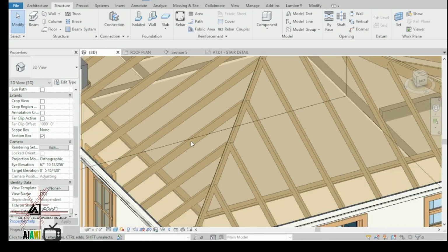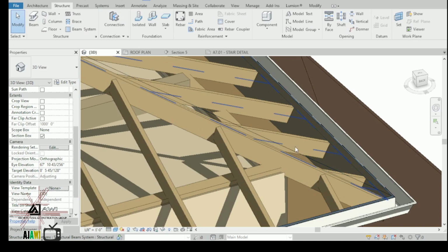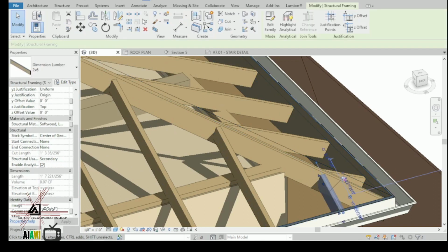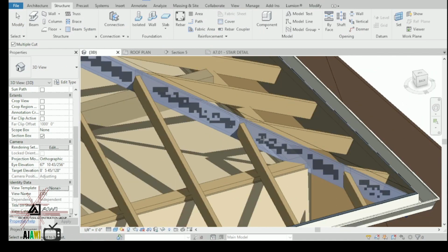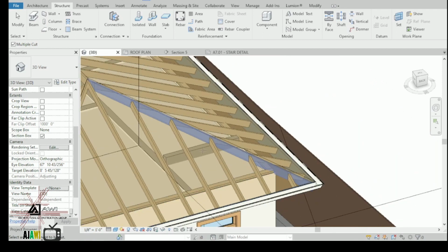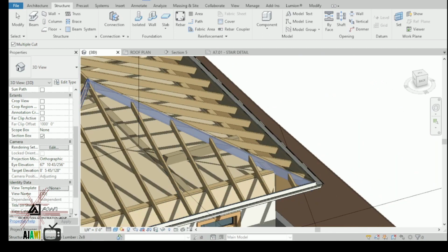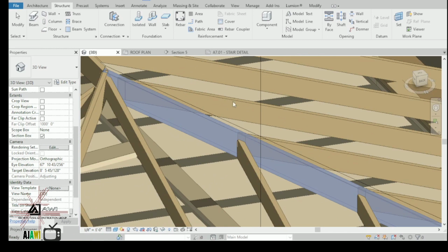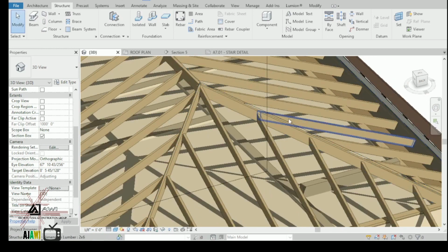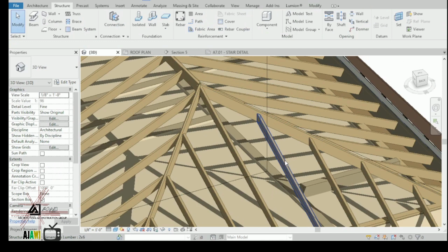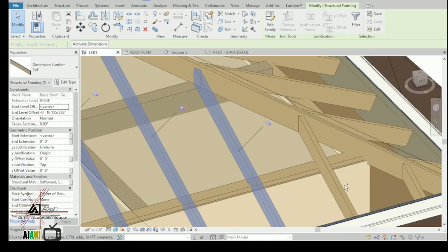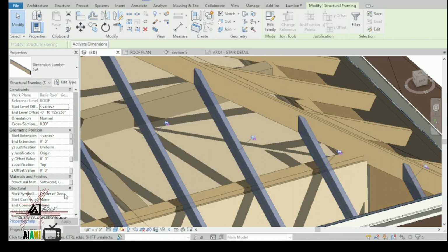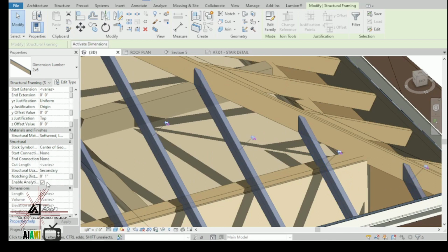So I'm going to this one now, then I click notch, and then I select what I want to cut it with, cut, and then I can just change it at the same time. My workflow is that I tend to like to do things immediately, so that I don't have to go back over things at times.